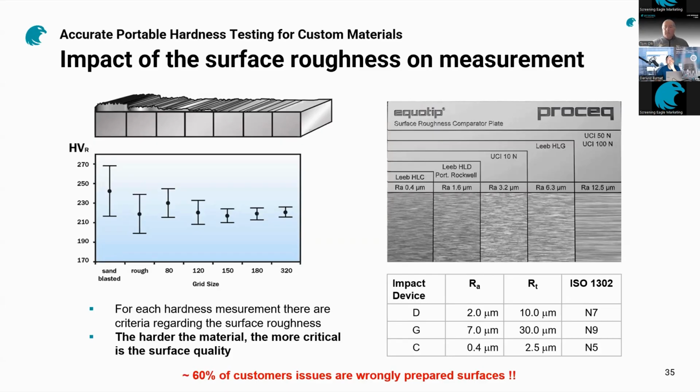The question reads, is a hardness measurement of HLCD the same as HLD? Sometimes I get sent an HLCD from an inspector. My answer would be I don't know, because I don't know what scale HLCD would be. That's an improper notation for a hardness scale.